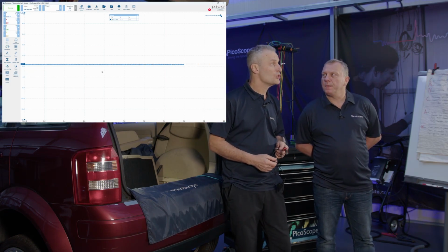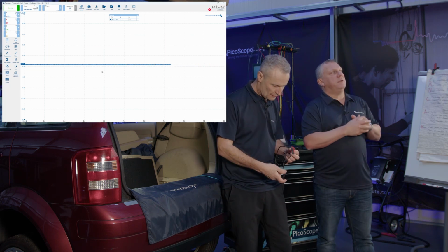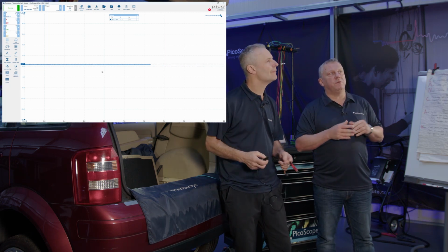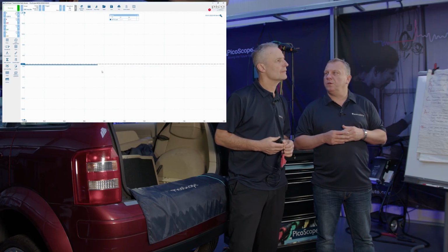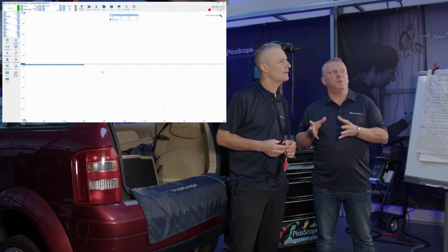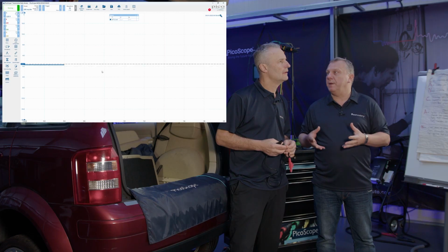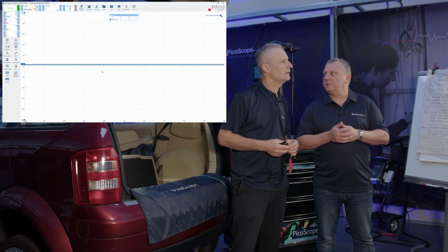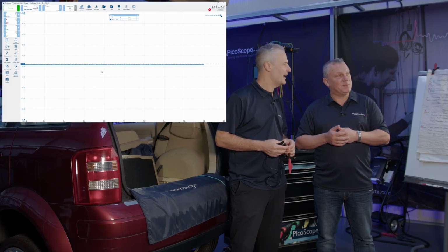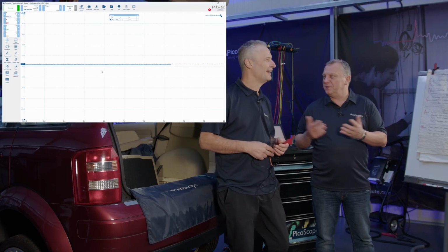Well, what we'll do, we'll short the two together. This residual voltage that we're measuring there could be enough to retain memory in certain components, and there are many components within the car that have memory. And often this is a technique that technicians use anyway, sometimes to get out of jail. Yeah, absolutely. So we're using it to make sure we're at 0 volts.